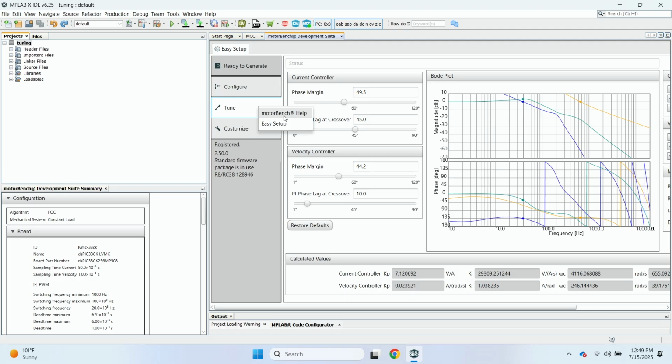In general, careful tuning from default values can improve performance for most motors, but improper tuning can lead to poor performance and instability in the control loop. The field-oriented control section in the latest release of the MCAF, the Motor Control Application Framework documentation, has more information on control loop tuning, which can help to make tuning easier. The link to the latest MCAF documentation can be found by opening the release notes, which can be found in the Release Collateral Master folder.